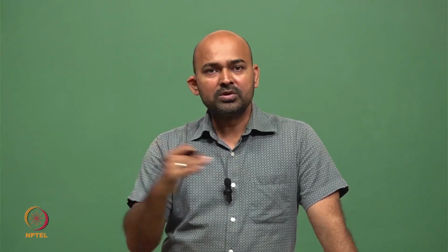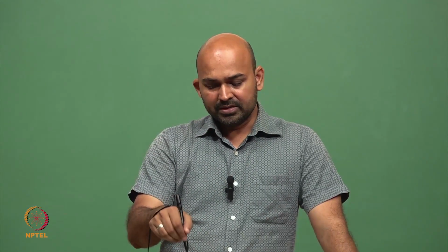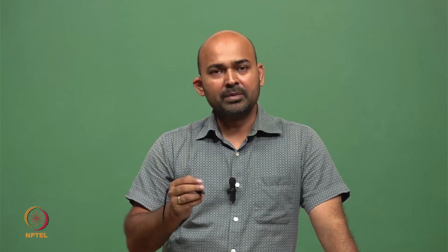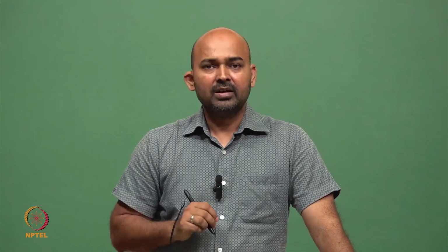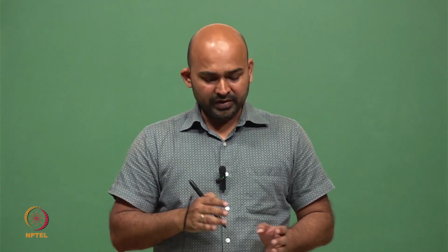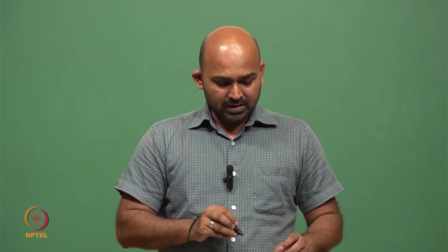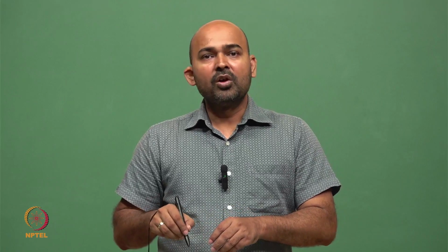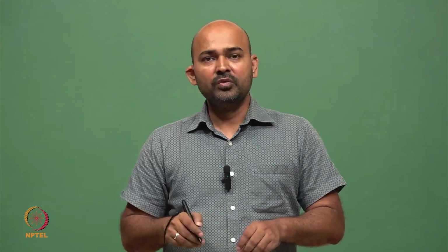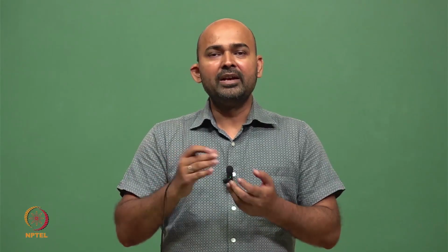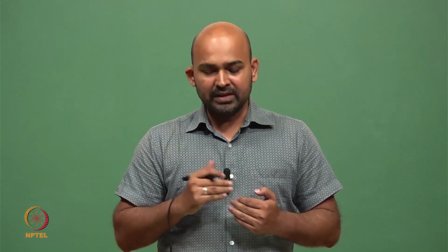Sin theta is the angle between the velocity and the magnetic field, and most of the time, because this magnet is perpendicular to the motion of electrons, theta becomes 90 degrees, so sin theta becomes 1, so we can neglect sin theta from this equation for the time being. So the Lorentz force applicable on these electrons is minus QVB, and depending upon whether it is an electron or a hole, the polarity of this force will be opposite in nature.